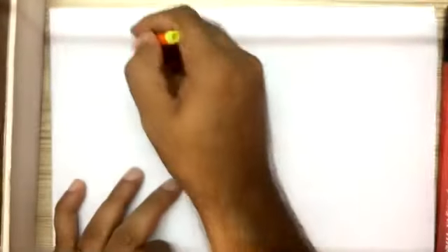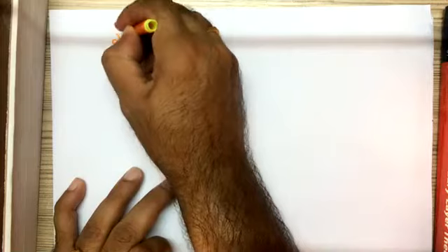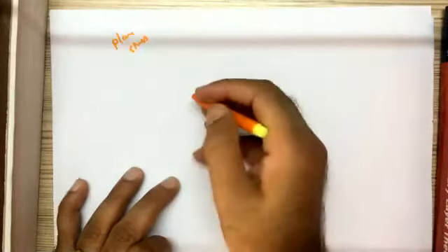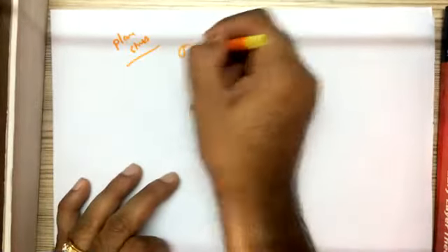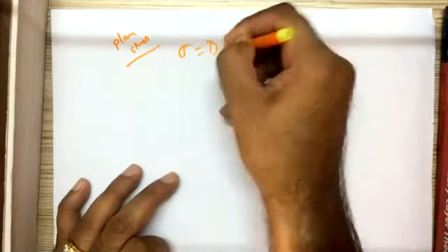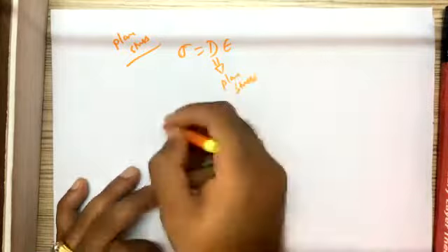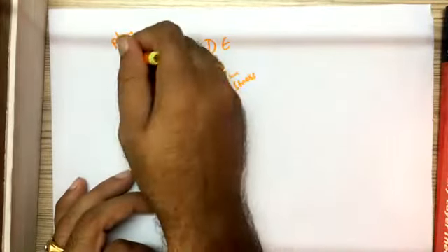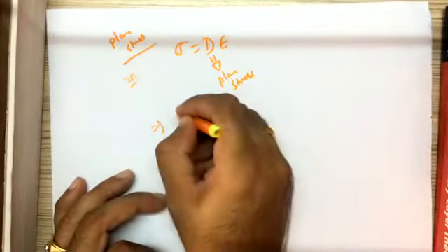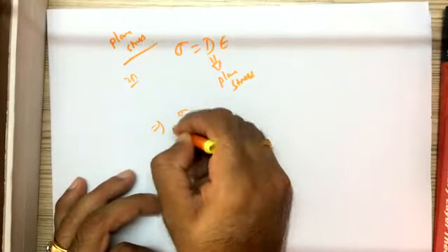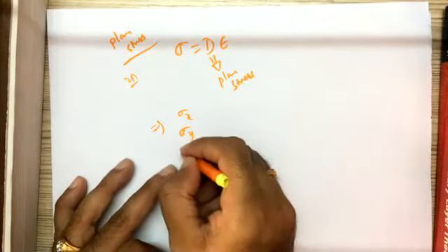One is, because it is clearly mentioned it is plane stress, we can go back to plane stress Hooke's law, sigma is equal to D into epsilon. What is D matrix for plane stress? What is sigma, by the way? It is 2D, so sigma x or sigma xx, sigma y or sigma yy, and sigma xy or tau xy